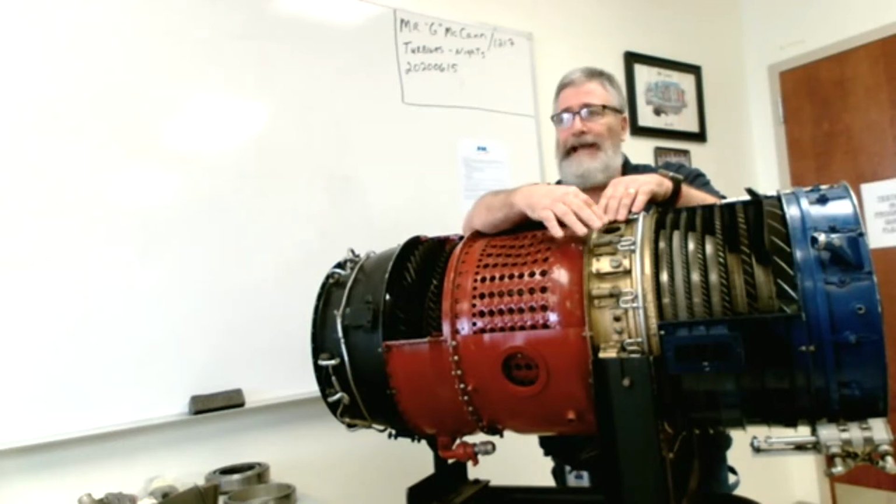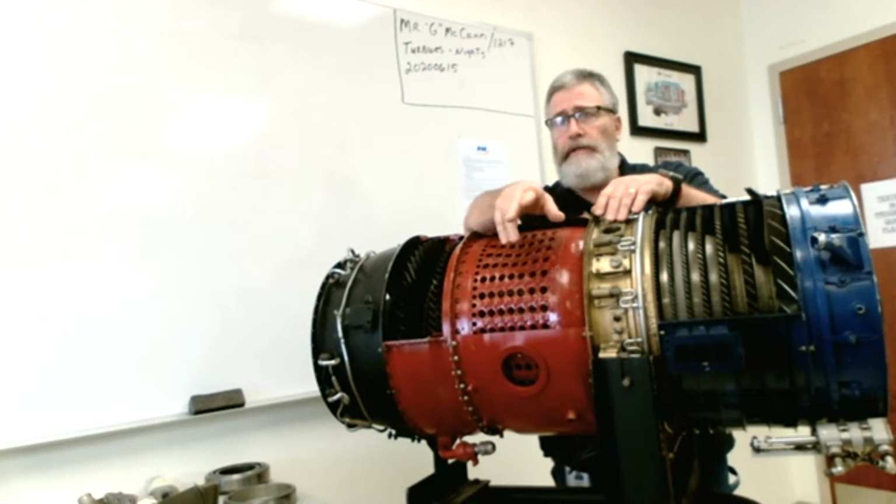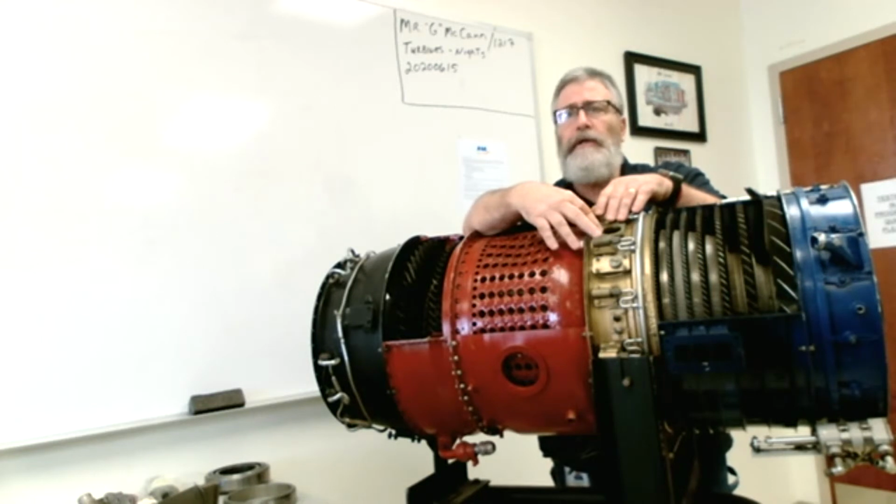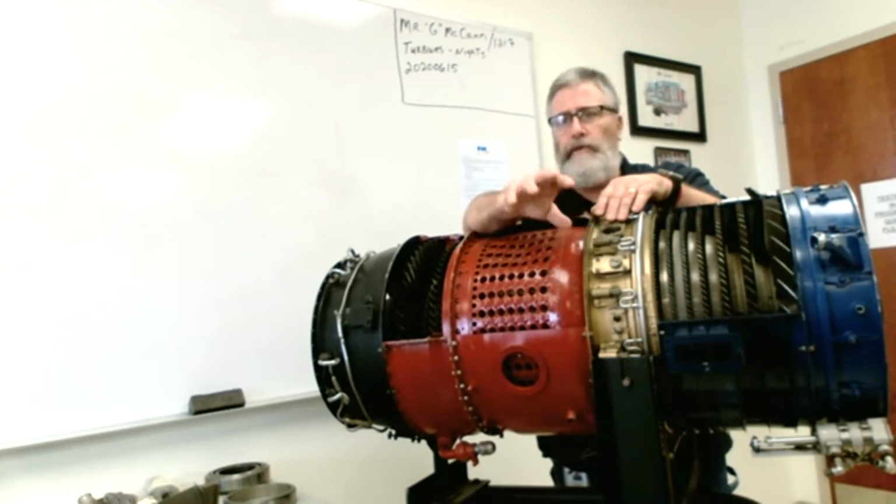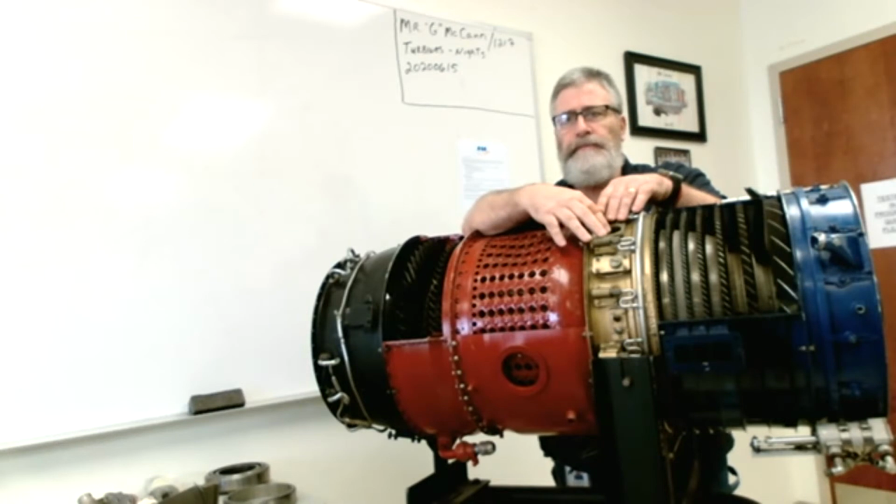It can provide anti-ice on a turbine engine. It can help with pressurization of the cabin. It could cross-start another engine on a turbofan. So basically, it's a good resource. We use bleed air a lot as a mechanism to activate other things.